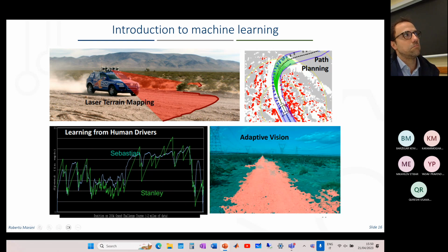But also in unstructured domains. So go back to Mars, let's say. Look with vision at the map, at your terrain, and make some path planning according to the optimization of a cost function. Let's say on Mars, maybe you are more interested in reducing the battery power required for your path. Maybe the shortest path is not the best for battery requirements. And you can also use this optimization, this model function, to define something different.